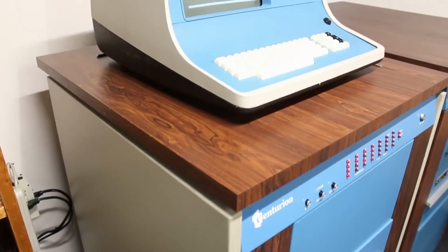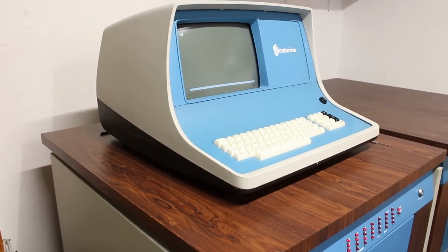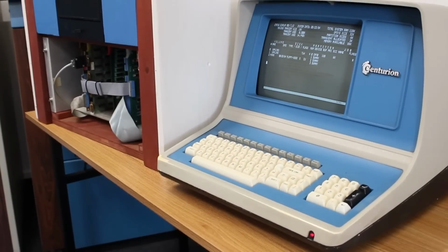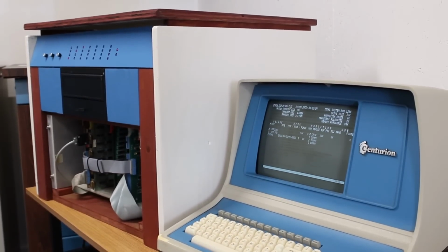I don't have to get the machine over there. I just have to get a terminal over there. And, well, the main terminal that's sitting on top, I can't really move. I cut the RS-232 cable to the exact length, and it's all snaking through. That one's not going to work, but I have another terminal for the mini Centurion. I can just plug that one into a spare port on the MUX card and run it over next to the machine. And, well, then it's remote access.